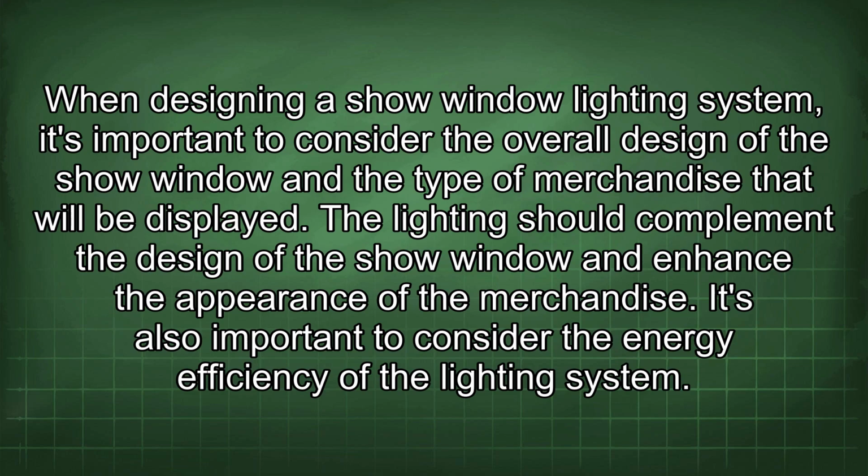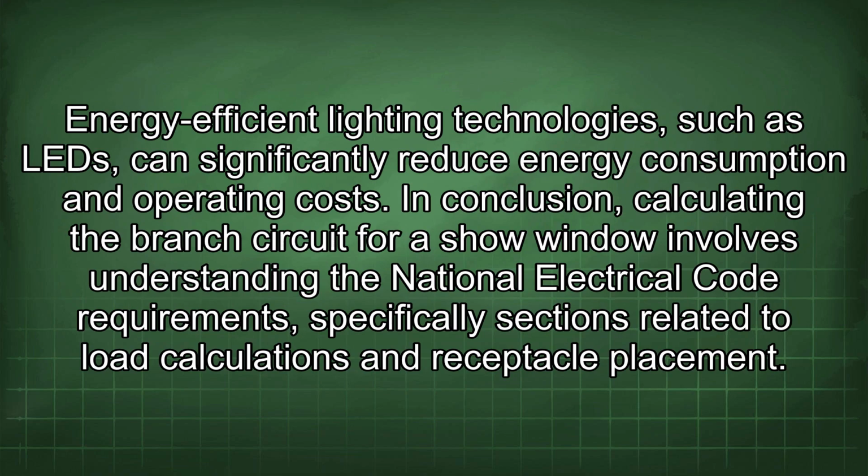When designing a show window lighting system, it's important to consider the overall design of the show window and the type of merchandise that will be displayed. The lighting should complement the design of the show window and enhance the appearance of the merchandise. It's also important to consider the energy efficiency of the lighting system. Energy-efficient lighting technologies such as LED can significantly reduce energy consumption and operating costs.